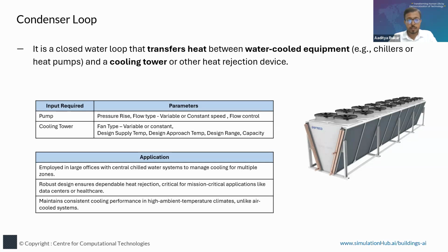So it is basically a robust system. It cannot be directly attached to your air systems, but for your chilled water chillers as well as for your VRF loops, you have to use a condenser loop if you are choosing water-type cooling.